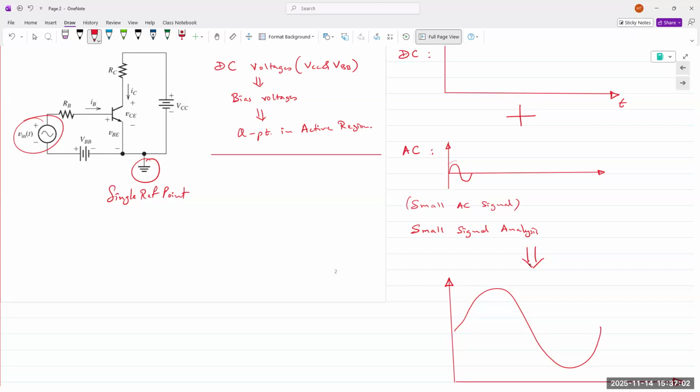That's not the way amplification works. The energy to amplify any signal comes from the DC biasing voltages, so obviously there's an upper limit on how much we can amplify a signal. If our DC biasing voltage is only 10 volts, we cannot expect an output greater than 10 volts. If it's 15 volts, it cannot be greater than 15.